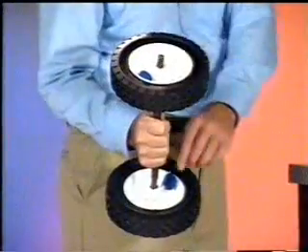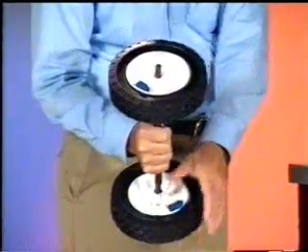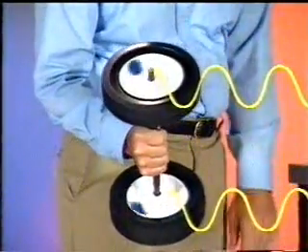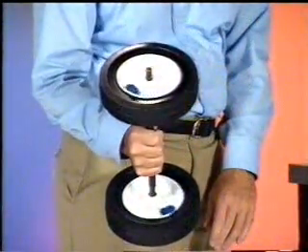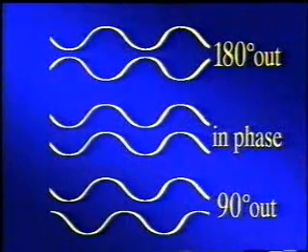It is important to understand that each revolution of the tire completes a full sine wave, and like the tire rotation, the corresponding sine wave is a full 360 degrees. When one weight is moved 90 degrees and the motion is traced, the sine waves will be out of phase by 90 degrees. With this example, we have been looking at the phase or relationship between the two unbalanced wheels. On a